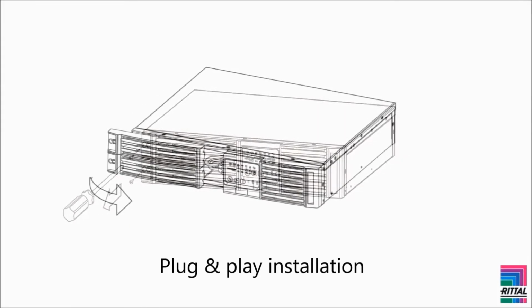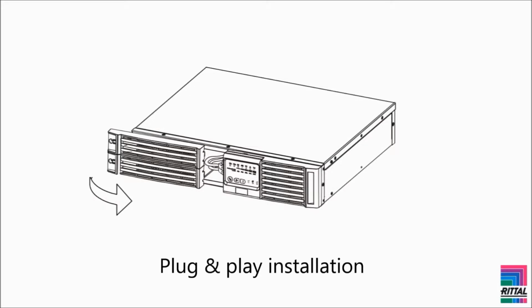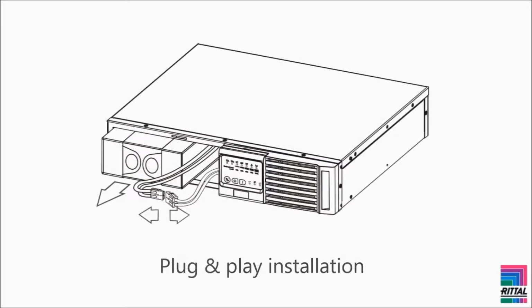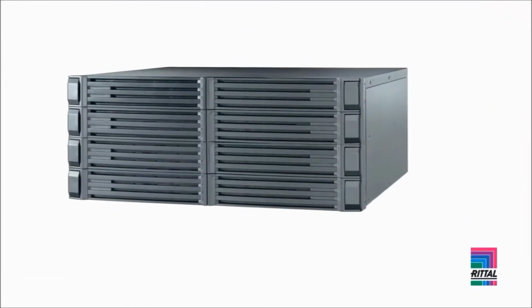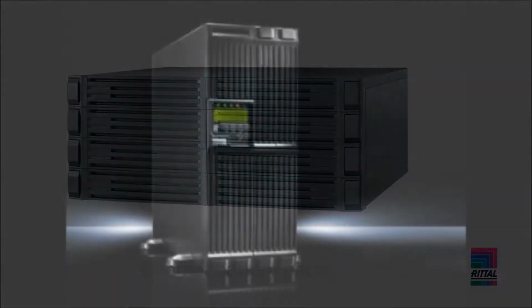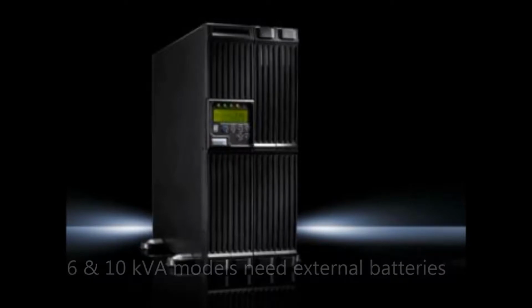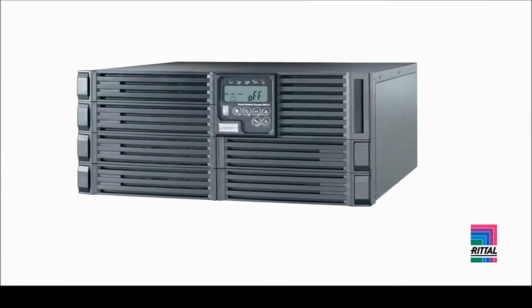The 7 amp-hour batteries have a 5-year life cycle and are easily exchanged from the front. Storage capacity can be increased for these models by adding external battery packs. The 6 and 10 kVA models need external battery packs, which take up 2 rack units. These models can also be paralleled with an optional parallel kit.